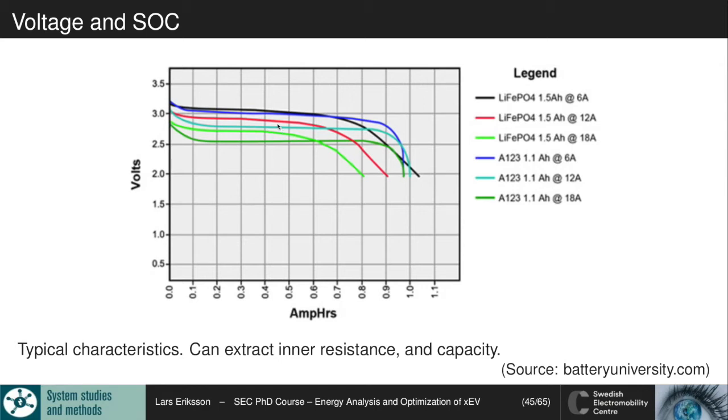And then we see it's a little bit troublesome because we cannot just look at the voltage to pull a conclusion of whether it's fully charged, whether it's charged, or whether it's close to become depleted. So this is a challenge for what is called state of charge estimation. While it's easier with the LFP battery here. For these 3, we see that there's a bigger connection between the state of charge and the output voltage.